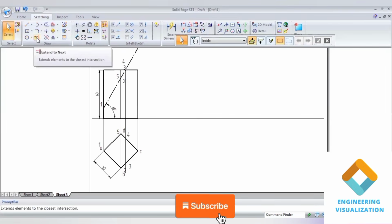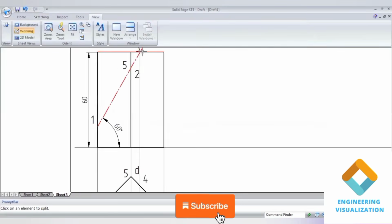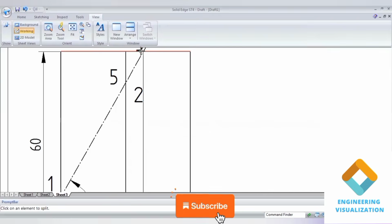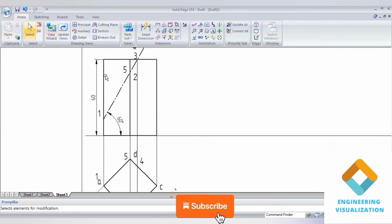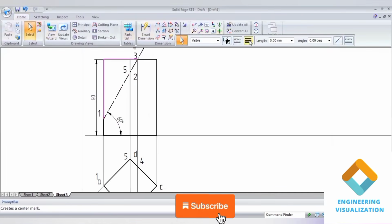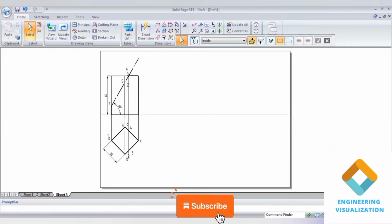Now we have to project it. I can use the split command to highlight only the retained cut portion. Using the split command we can split it exactly where we want to make the lines dark. We have to darken only the portions which have been cut by the section plane, the retained cut portions. The other lines I'm going to make thin lines. By selecting these lines, I'll make them thin lines.